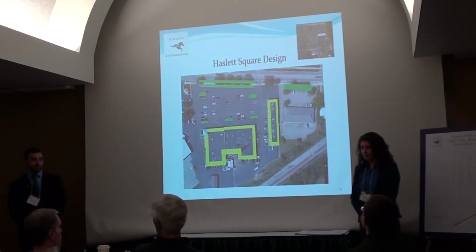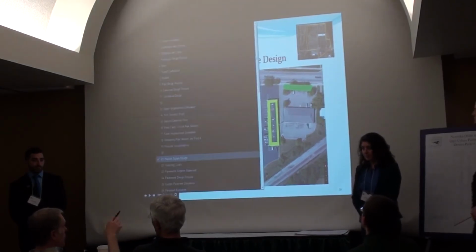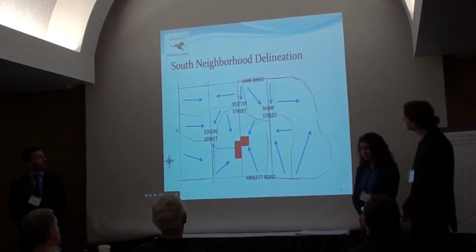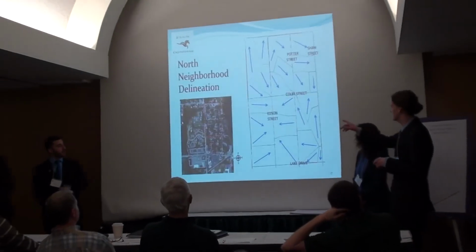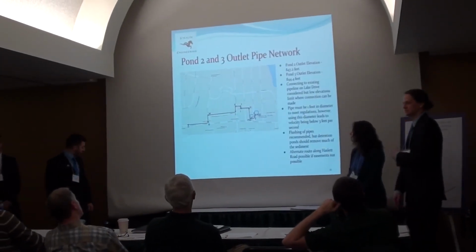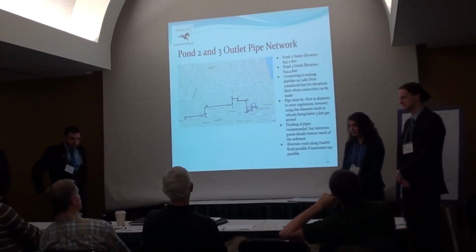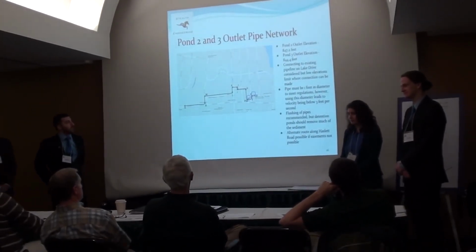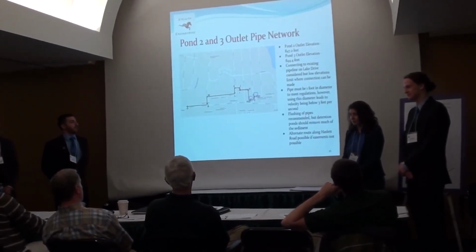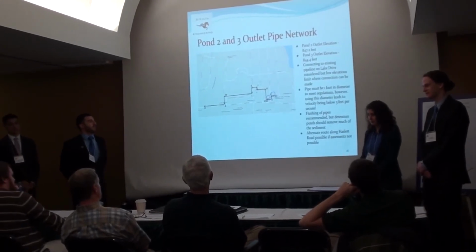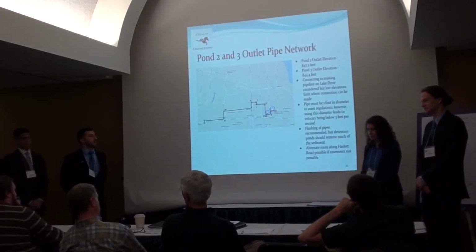Can we look at the graphic that shows your layout for the southern of the detention ponds in the Mocha Village plat area, where you show your line running out to the outlet drain? Yes, right there. I've got some real issues with your willingness to violate some basic design criteria, such as your low velocities in the pipe, knowing that you've got some downstream issues in the Pine Lake outlet drain.